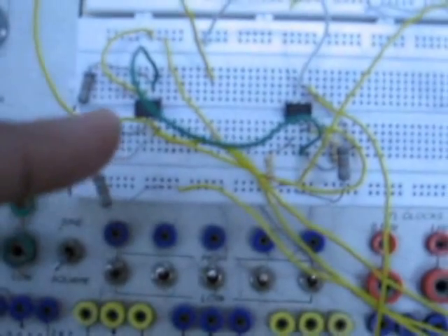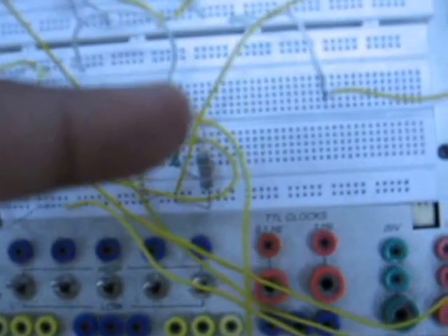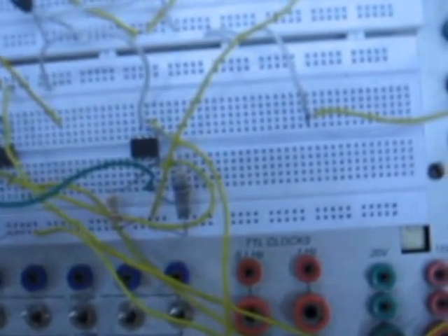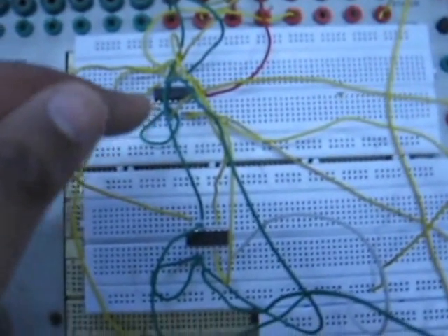they're filtered. Next, they go to this amplifier block, where they're amplified, and then on to the comparator block. In the comparator, there is a given threshold, and if the comparator output is low, it triggers this counter circuit on.